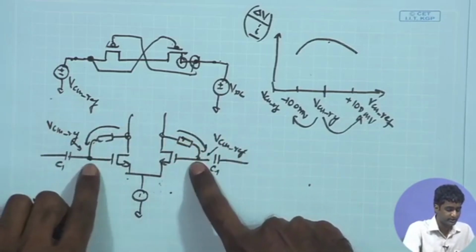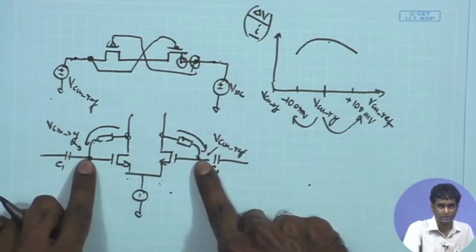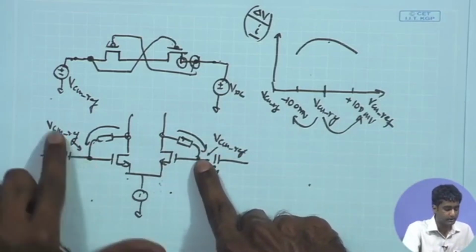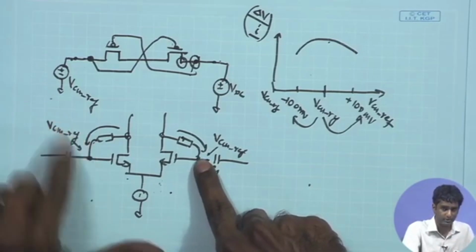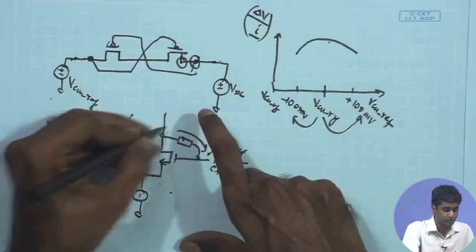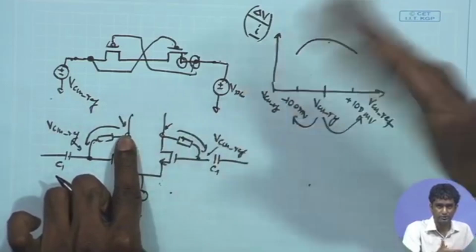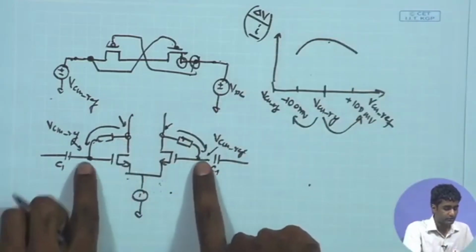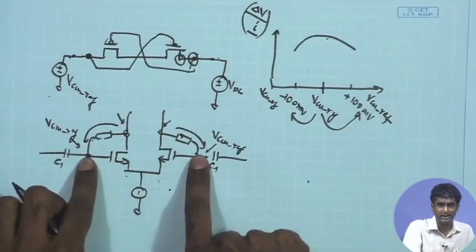You are initializing this potential. That means, rather than starting with a random DC potential, the simulator will start by putting these two potentials at the VCM ref, and in that case, since these two potentials are anyway quickly set to the VCM ref by the help of common mode feedback, which is going to operate much faster, it will ensure that in the long run also, as your simulation goes on, this potential is maintained at VCM ref.